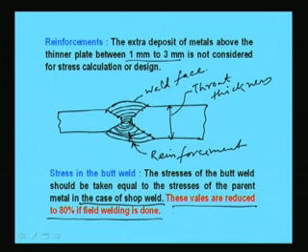So, in the case of butt weld, whether it is shop weld or field weld, we have to know. If it is shop weld, then the stress will be equal to the parent metal stress. If it is field weld, then 80% of that will be the allowable stress. This will be clear if we go through one small example.